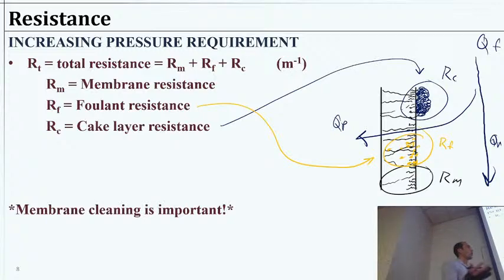So that's a little harder to clean. Maybe this is where we might want to use chlorine or something, or an acid wash or something like that to try to dissolve or eat away anything that we can. You know, a ceramic membrane you might be able to pour drain cleaner on it and it's just gonna zap any of the organics. A polymer membrane, you'd probably be ruining your membrane in a split second.